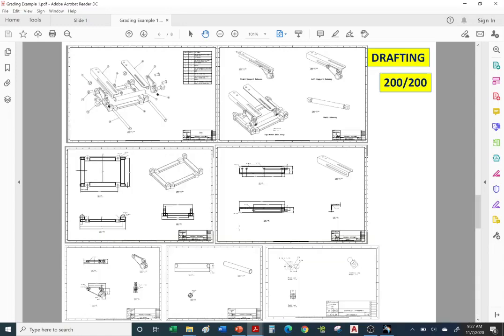All right, so we're going to go back to the drafting workbench or drafting lecture. Okay, so you are to create a drawing like this one. Here's an example from one of my old students. Okay, so you're going to create a title block and border, parts list, an exploded view, a top assembly, sub-assemblies, and you're going to create the detailed drawings of the individual parts, the base plate, the bracket, the support, the shaft, and the knuckle. We do not make drawings of the hardware, the bolts, nuts, and washers.